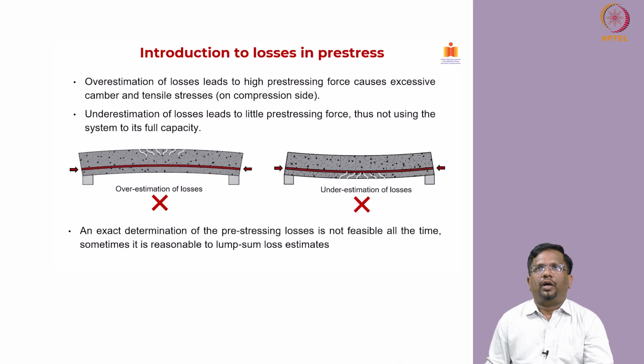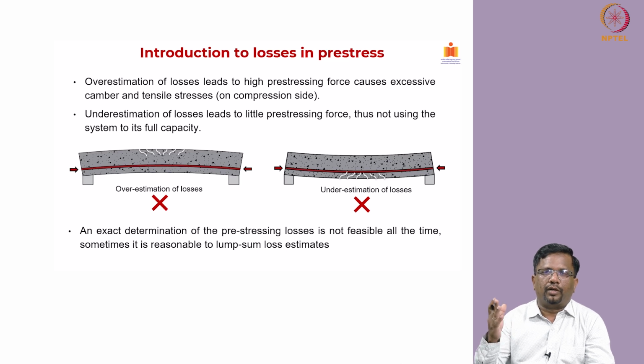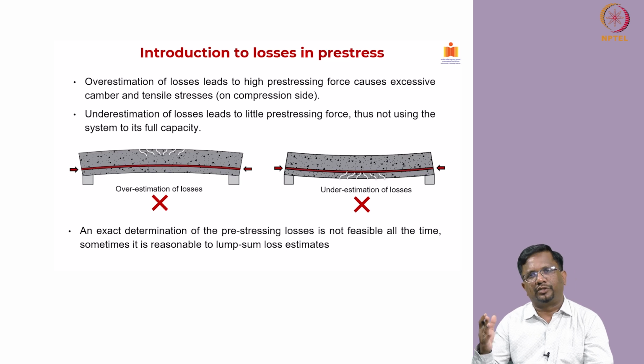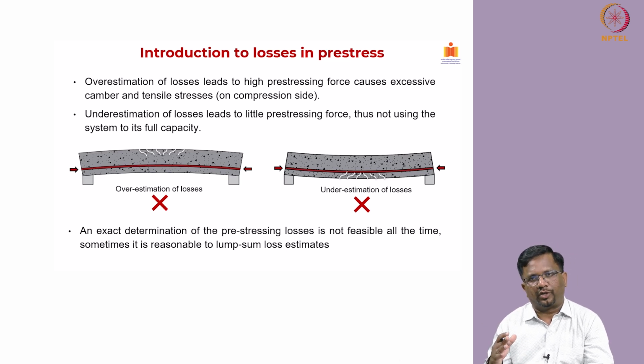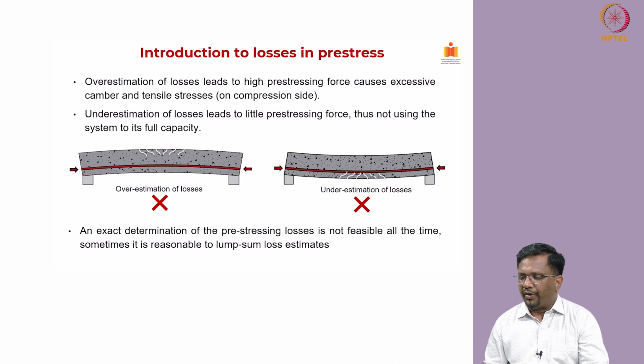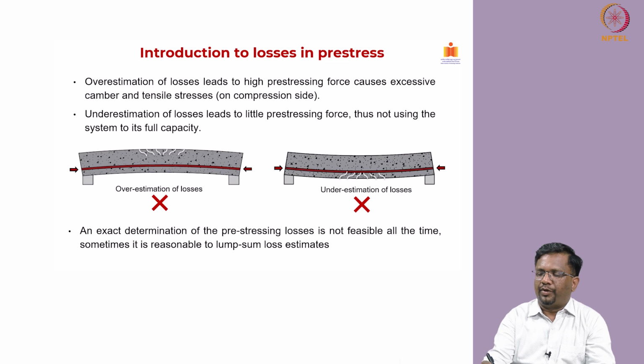Now, why should we be concerned about losses? Depending upon which time you are evaluating the stresses or the condition of the element that we have designed, we have to account for both immediate or short term losses as well as long term losses. Now, when we do that, sometimes if you overestimate the losses, it can lead to high pre-stressing force in the initial design.